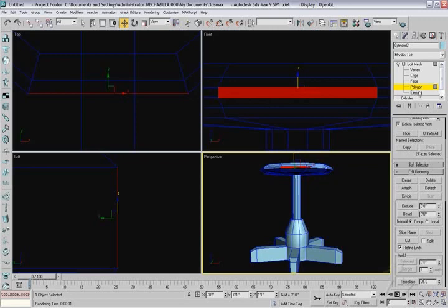So as long as we're in polygon mode, we have a new tool to introduce to you. Under Edit Geometry, we have the Cut tool. Now, what this allows us to do is place our mouse over any edge, and we can click on it, and you'll see you get a marquee handle, and wherever you place that, like over a new edge, including invisible edges, it will turn into a plus. And I'm just going to put that on the other side of my selected polygon and click,